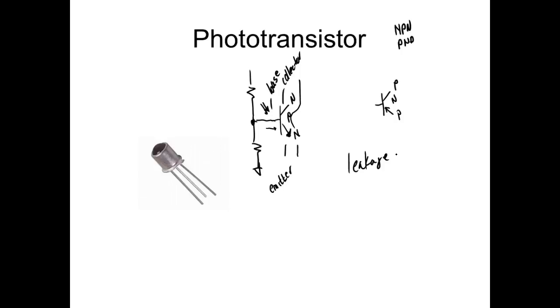So phototransistors: the advantage of phototransistors is they're extremely fast, and we can get a lot more current out of them than out of a photodiode. All we get out of a photodiode, guys, is something we call leakage current, or leakage current change. Normally, it's in the range of nanoamps, so you can't get much work out of nanoamps. This one depends on the size of the transistor, but milliamps, very easy to get milliamps. We get amps out of these, but not out of photodiodes, regular transistors.